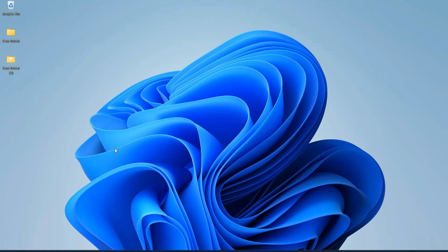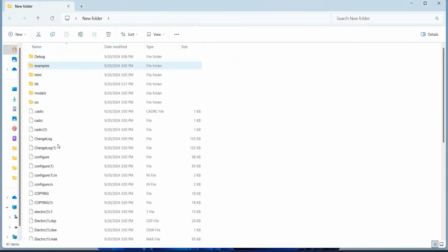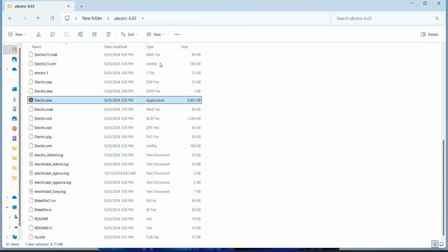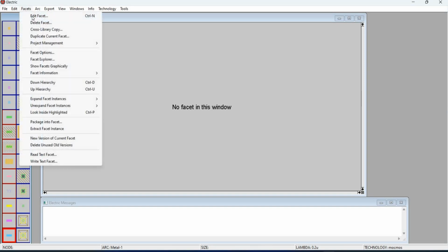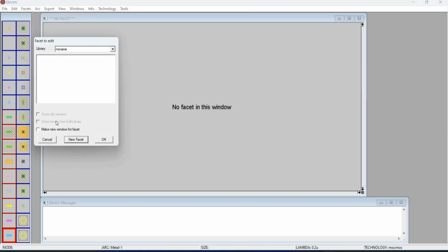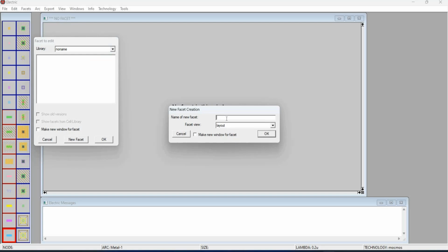For today's video, we're going to use Electric 6.03, so the older version of Electric, as well as WinSpice and LTSpice. We just need to click on the Electric software, then edit facet, so new facet.